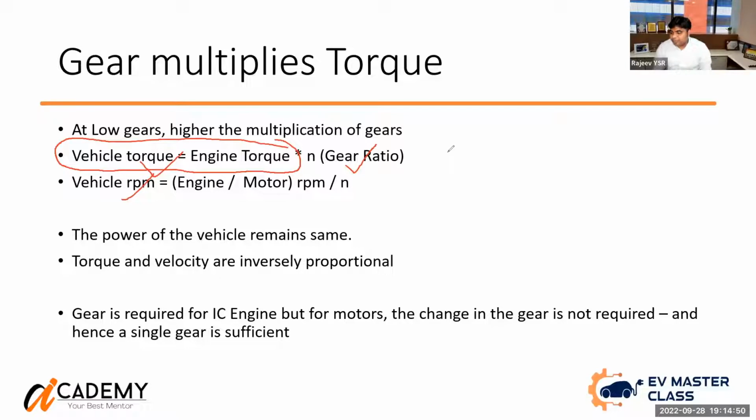That's a good question. Do we have a gearbox in EVs? I'm going to answer. There are multiple constructions of EVs, my friends. In certain EVs, there is no gearbox. For example, most of the time in two-wheelers, it is directly the hub motor where the power and torque curves are controlled by microcontrollers or processors. The programming will take care of all of this. In certain cases, there is a transmission, but not necessarily through a complicated gear structure like that of an ICE vehicle, but a simple one-step gear. So both constructions are possible in vehicles.